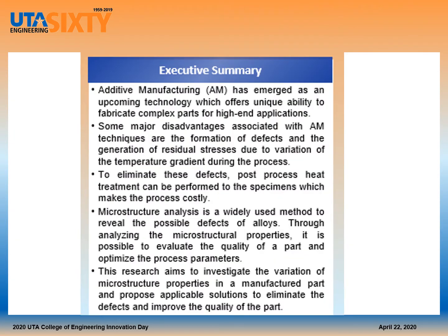To gain insight, additive manufacturing has emerged as an upcoming technology which offers a unique ability to fabricate complex parts for high-end applications. Some major disadvantages that this poses are the formation of defects and the generation of residual stresses due to variation of the temperature gradient during the process. To eliminate these defects, post-process heat treatment can be performed on the specimens, which makes this process costly.